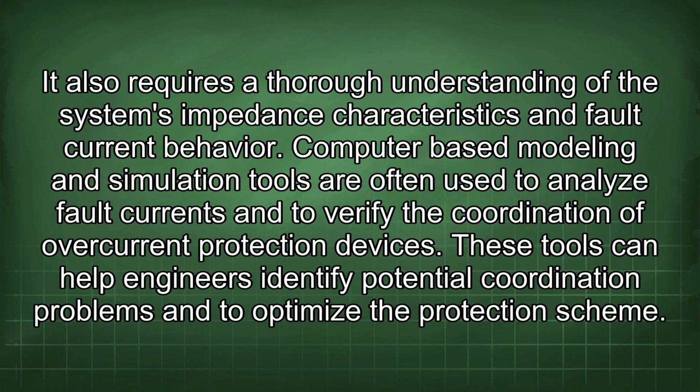It also requires a thorough understanding of the system's impedance characteristics and fault current behavior. Computer-based modeling and simulation tools are often used to analyze fault currents and to verify the coordination of overcurrent protection devices. These tools can help engineers identify potential coordination problems and to optimize the protection scheme.